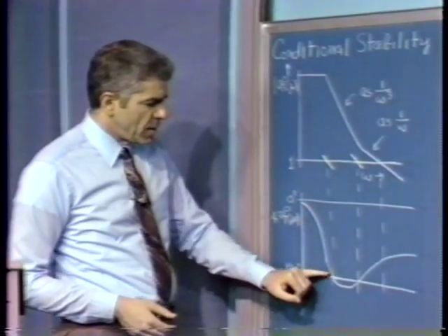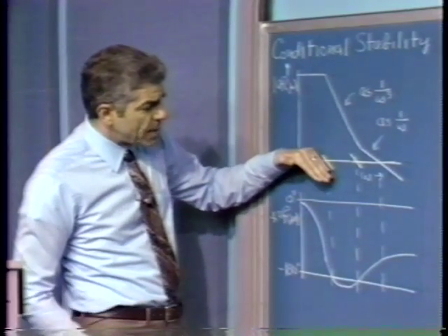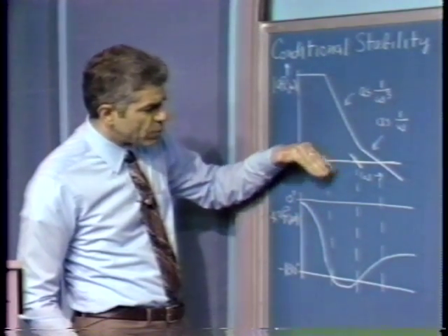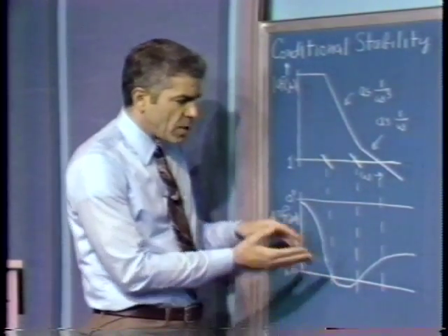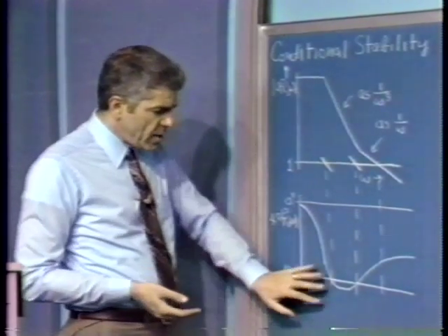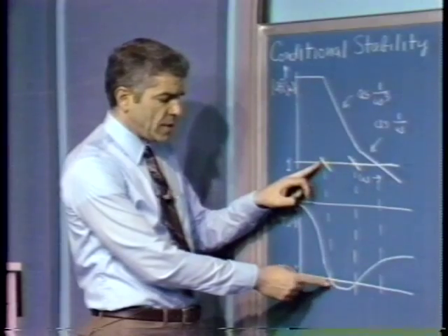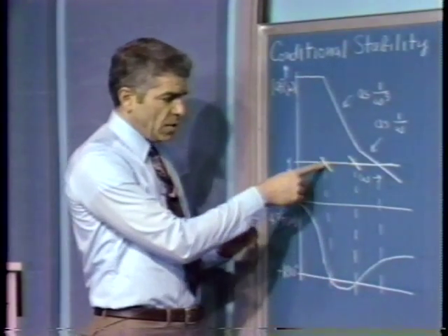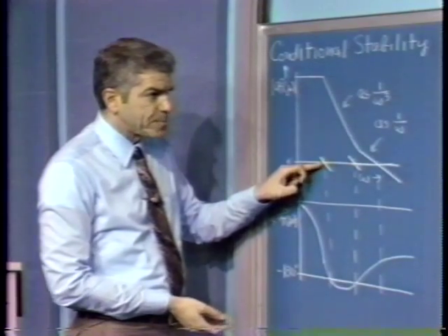Similarly, if we assume the magnitude decreases a little bit, the gain in the describing function sense goes up. We cross over at a higher frequency, a region of negative phase margin. The amplitude grows back to its original value. So here the system's restorative, and consequently we'd anticipate the system would oscillate with parameters such that E was large enough to force crossover at this frequency.